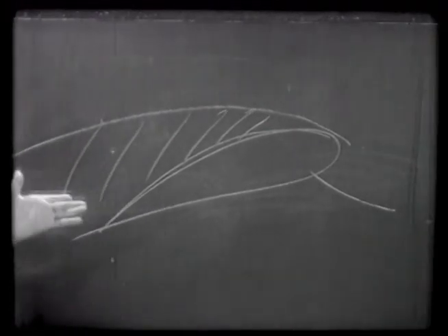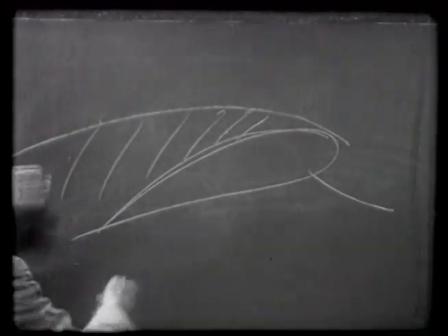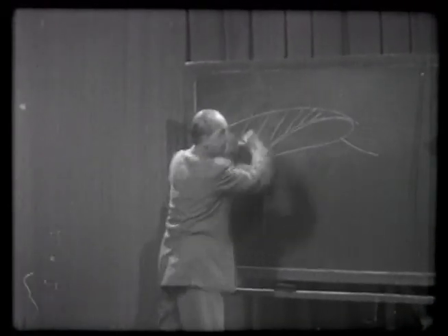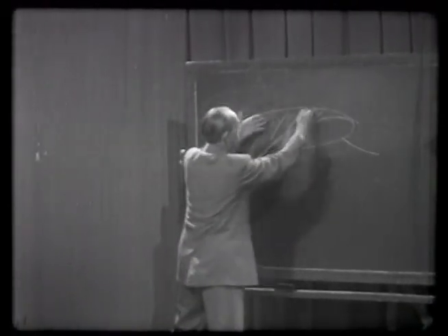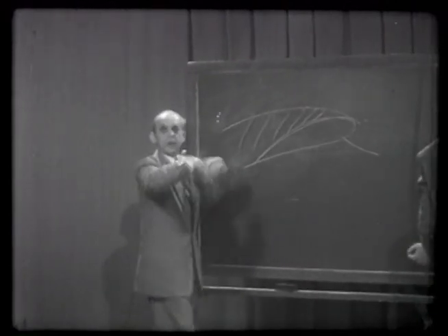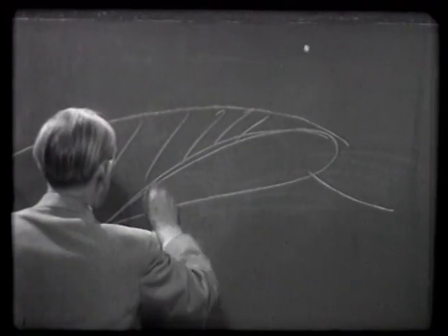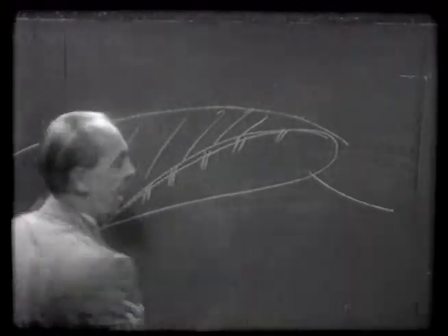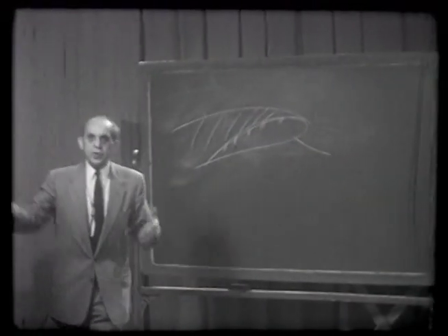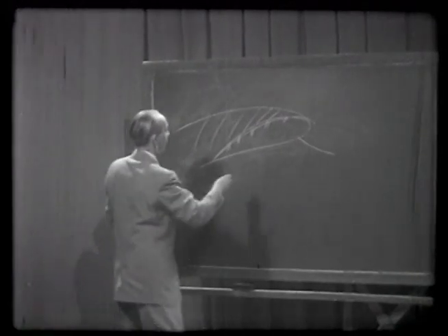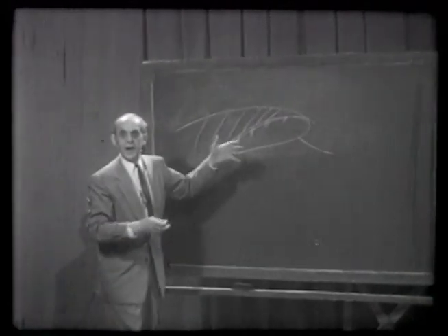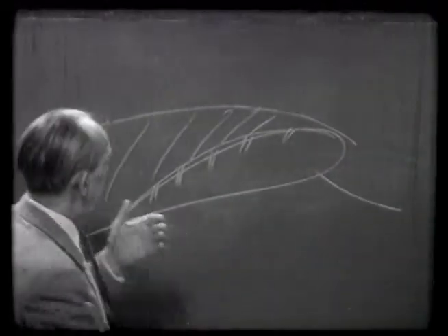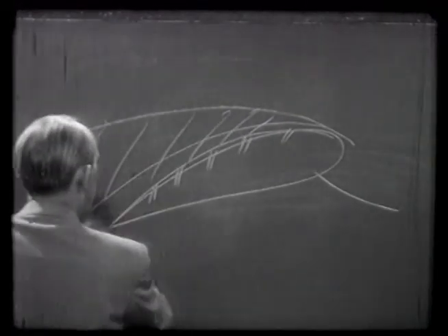Well, you could bring it back probably by taking this air, which has lost its energy, which has lost its momentum, take it away. Make some little slots in the surface and put suction into the wing and suck the dead air zone away. And then it would stay attached.